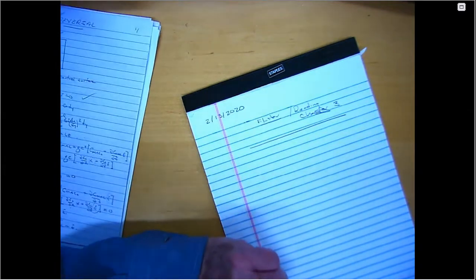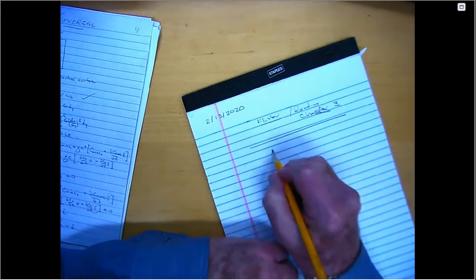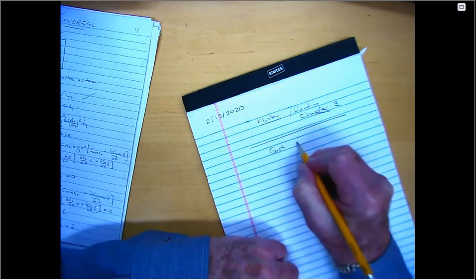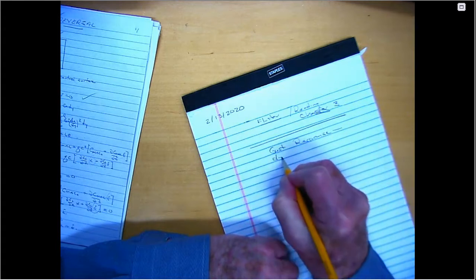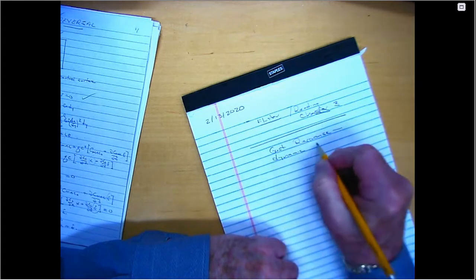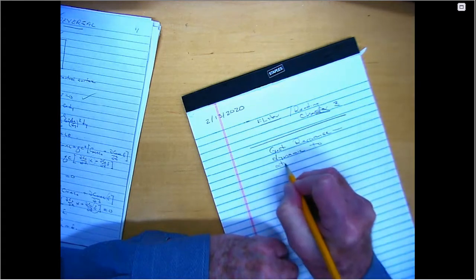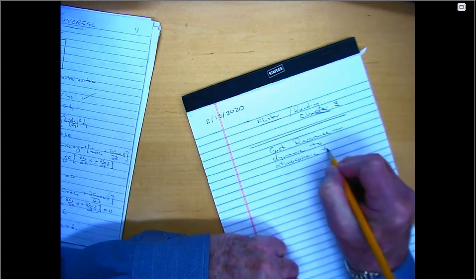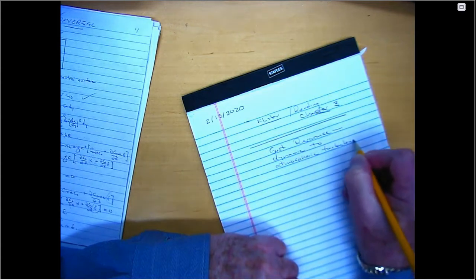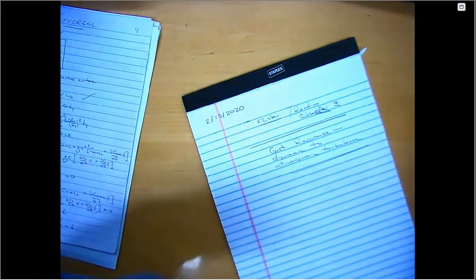On the other hand, there's another phenomenon that we'll treat later on called gust response, and that's the dynamic response to atmospheric turbulence, otherwise known as gust. So just as there are two great physical phenomena in static elasticity, namely divergence and reversal, there are also two prominent phenomena in dynamic elasticity, namely flutter and gust response.